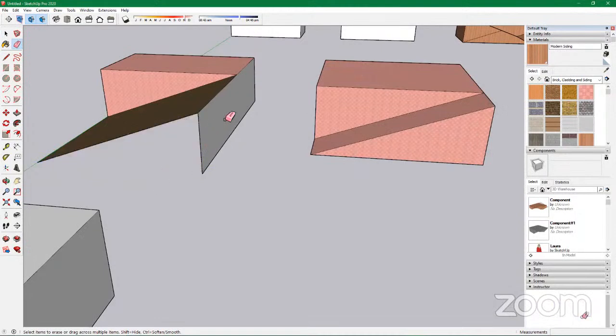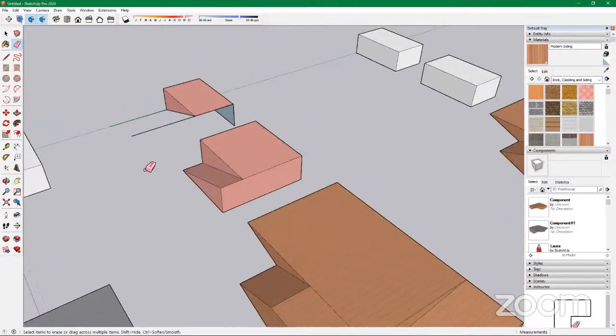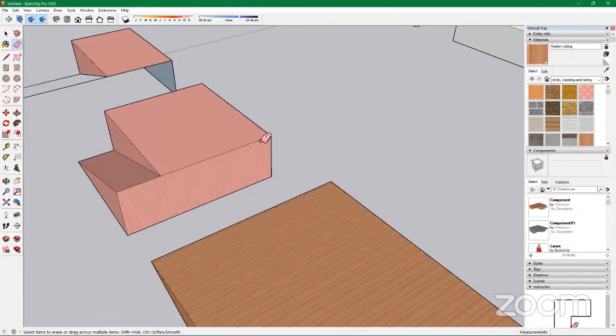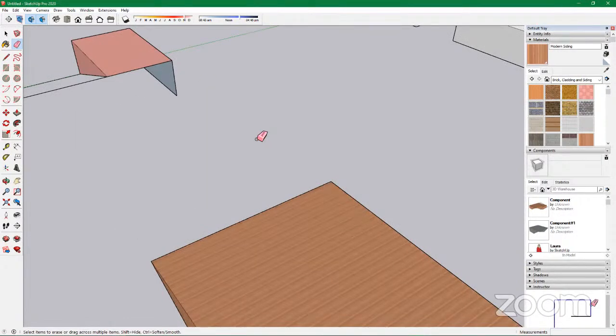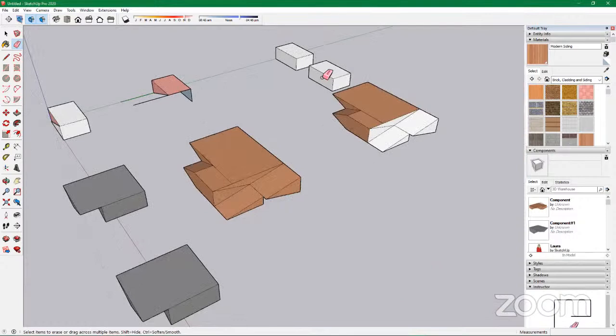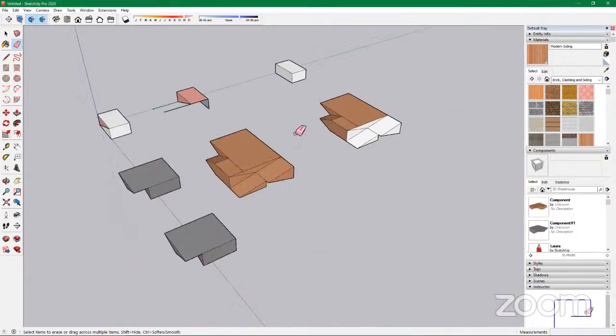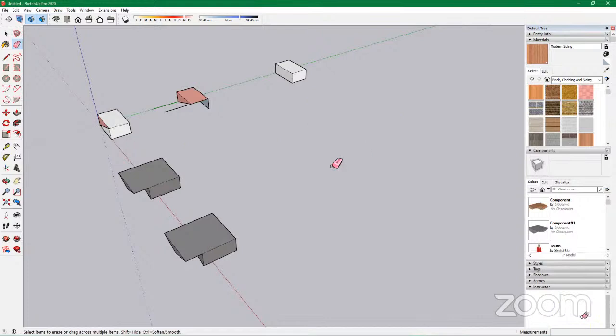That line is gone. If I erase this line, this face will be off because there will be no connection between these 2 points to create a face. So you see, and erase this line, and erase this line like so. That's for the ones that are not grouped or made a component. So now for the grouped ones, once I select any part of it, everything goes because they are all connected. Same goes for the components, everything goes. Do you understand?